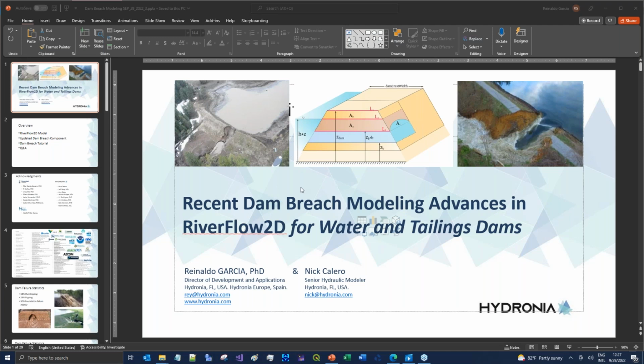Danielle asks if she can use as input a volume elevation curve instead of an initial water surface elevation condition when computing the dam breach. Actually, you can import a raster for the initial elevation that is variable in time. We do not have the option of a volume elevation curve for the reservoir, but that's something that we could develop. It should be a good addition, I suggest.